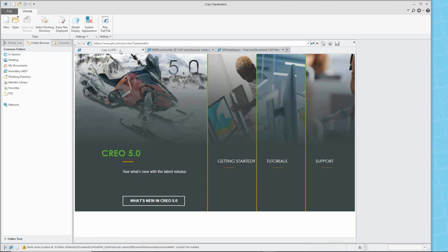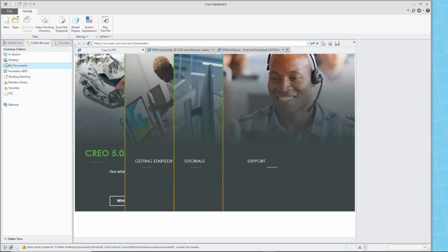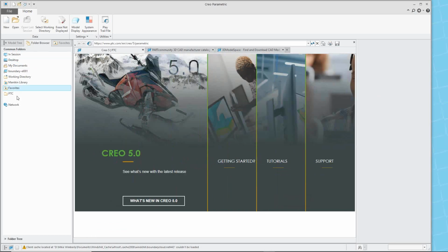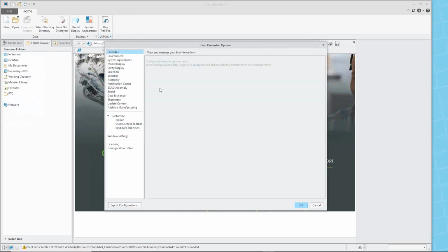So one of the things that we can do right up front is to simply go through and remove those and have our home page go to a local site, or basically a local folder on our hard drive. So that's going to be one of the first things that I do. And what you'll see throughout this presentation is that I will be starting and stopping Creo several times, where you can see the information locked in. So I'm going to go ahead into my configuration file that's underneath the file options. We'll go through the different areas inside of here as well.